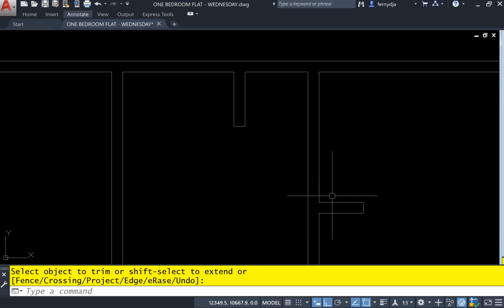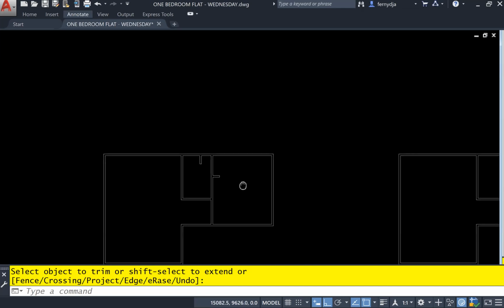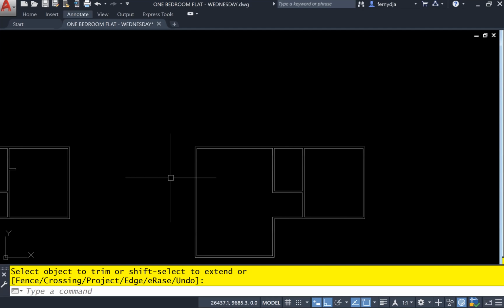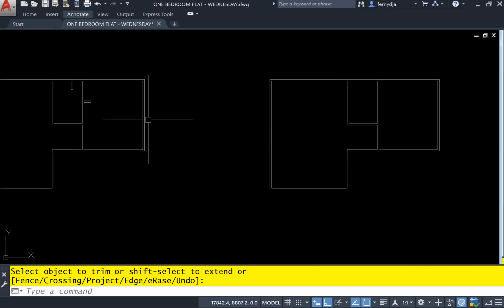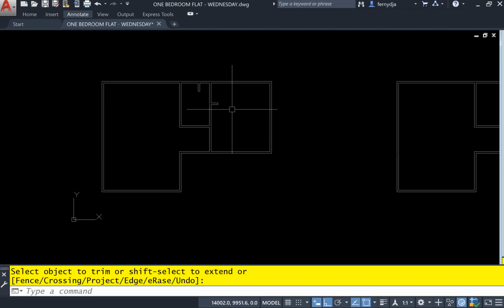The reason why I waited until after I copy this over here to put in those walls is because there is no need for me to excavate foundation, to put waste concrete, waste steel, and all them things on time, excavating foundation for a wall that will only bear its own weight. It's not going to be transferring any load from above coming down. So these closet walls, they don't need any foundation. So we make a copy of the drawing before we start putting in any closet wall and before we start creating any door opening. Everybody understand that?